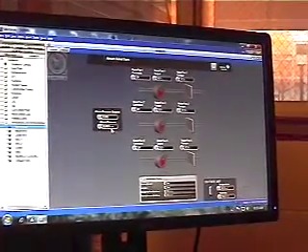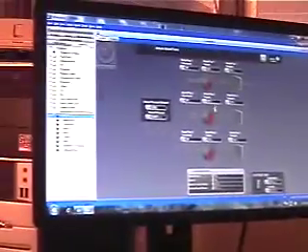Ideally, you'd want to keep the set points about the same. You don't want to get them too far, and we can create a general building pressure set point if you want, if it becomes an issue. You just don't want to have 0.08 inches here, you create a kind of a wind tunnel. There are 2 different systems for the relief fans, but these all will modulate together.